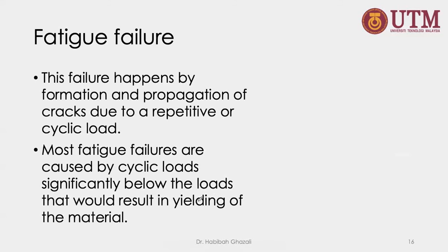Even with a very safe safety factor, say a factor of safety 2, meaning that it shouldn't fail, actually it may fail. So that's the reason you need to consider fatigue failure if it involves cyclic load. If it's static load, no issue at all.